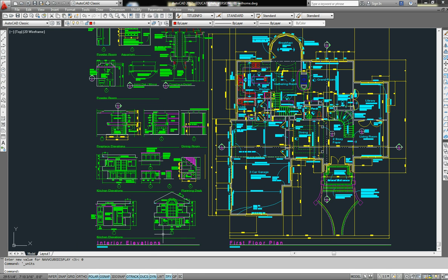The next thing we want to make sure we have turned on is the dynamic input, which is DYN here. Simply what that's for is when we use any tool, say the Line command, notice that next to the cursor I get these coordinates showing up and these little directions that say specify first point and so on. That's a useful and convenient tool. If I turn DYN off, I only have the pointer there. I still get the information displayed down here and in the command prompt, but I find it easier to use the dynamic input because the information's right there when you're drawing your commands.